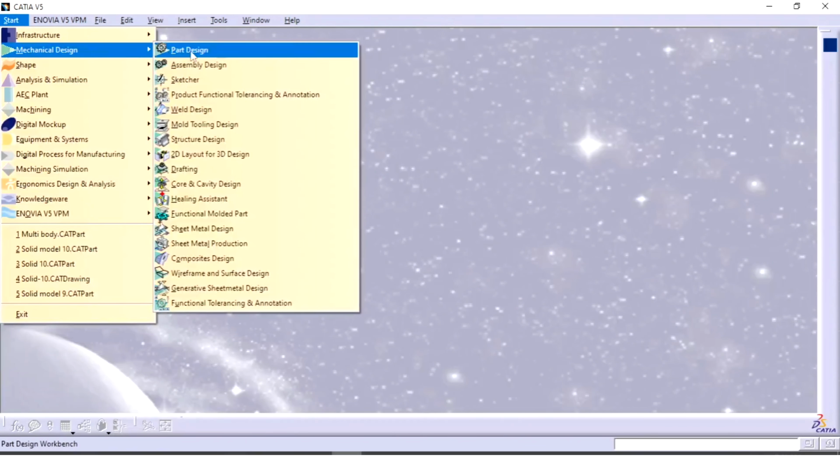Now we will go to Boolean operations, and we will combine these different bodies using Boolean operations to create the final output. Before that, we will learn about the different types of Boolean operations. CATIA provides 6 Boolean operation tools: add, remove, intersect, union trim, remove lump, and assembly.